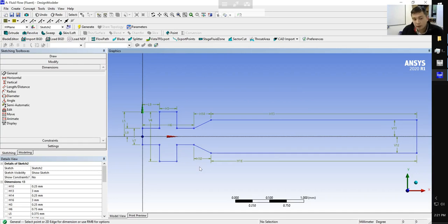So we've gone ahead and added dimensions. Notice we didn't plug in any values for those dimensions. We didn't actually change the sketch at all. What I would say is you don't necessarily have to have your sketch fully defined, but you do take the risk that there's potential ambiguities when someone else is trying to implement your system. So I'll obviously be posting a PDF with all of the dimensions included here. But at this point, we're done with our sketch.